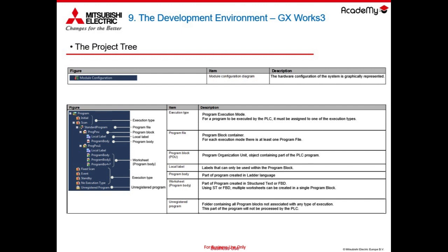Nothing prevents dragging and dropping the program file or the POU towards another folder, such as fixed scan, because you choose to work in another execution mode. So in this case, we have a program file called standard program that will go into scan mode because it was inserted under the scan folder.